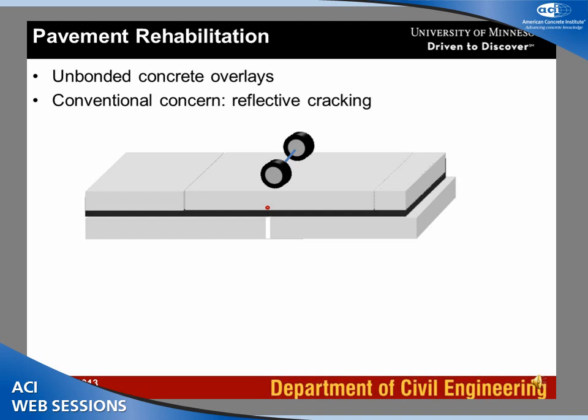Partially because if you try to simulate this system in Abaqus or in the latest version of iSlab, for example, it always predicts very high stresses above the crack if you place the load on top of it. And we understand that most likely the stresses are fictitious, they are not realistic, but still they have to be accounted for.